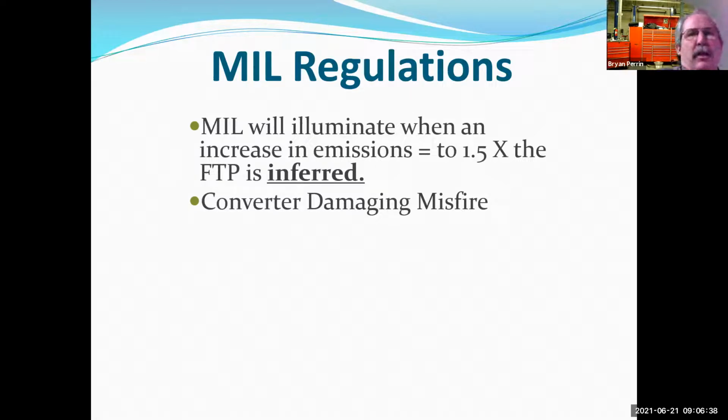Catalyst damage happens a lot earlier than what it takes to melt down the ceramic substrate of the cat. You got to be over 4,000 degrees to hit meltdown of the ceramic. So, I mean, you're talking extreme heat. We start doing damage to catalytic converters at 1,462 degrees. That's when we start melting the first element in the catalytic converter that causes it not to work. So I'm over 4,000 before I finally melt it down, but I'm destroying it at 1,462. So you can see where it just doesn't take long.